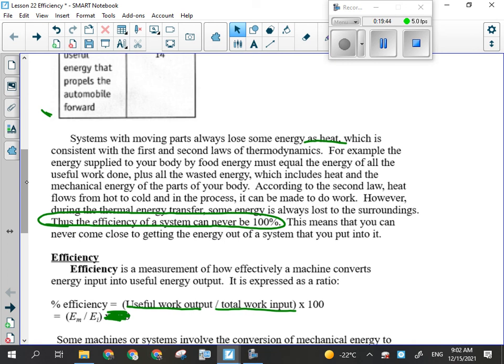If there were ways to eliminate some of those steps, yes, there would be. So we look at different ways to generate electricity. If we're looking at not using fossil fuels to generate heat and going directly to mechanical energy, that's more efficient. So the wind farms down in Pincher Creek are more efficient because they're going mechanical energy to the generator directly rather than converting it to heat, heating water, turning water to steam, and then turning a turbine with the steam. They're eliminating some of the processes, so they're more efficient. A solar panel turns solar energy directly into electricity. That's more efficient. That's a direct conversion to electricity as opposed to a bunch of transformations in between. Do they generate as much? Are they as consistent?